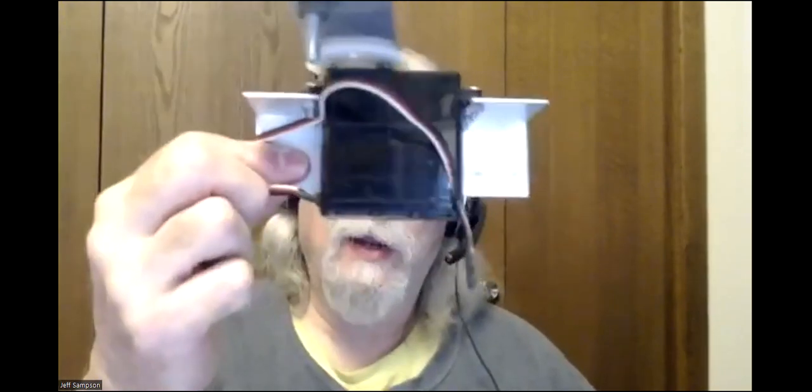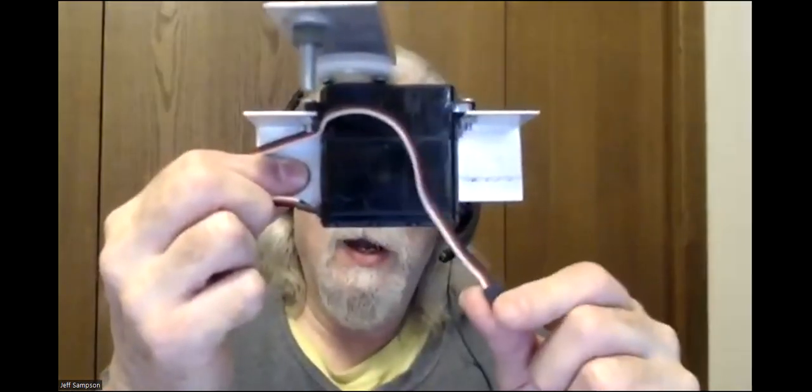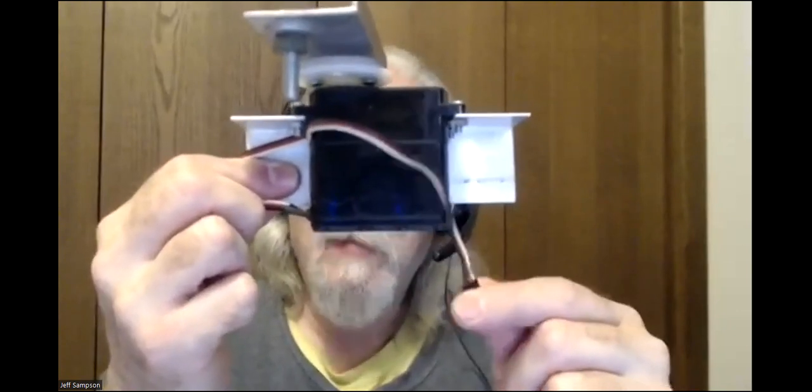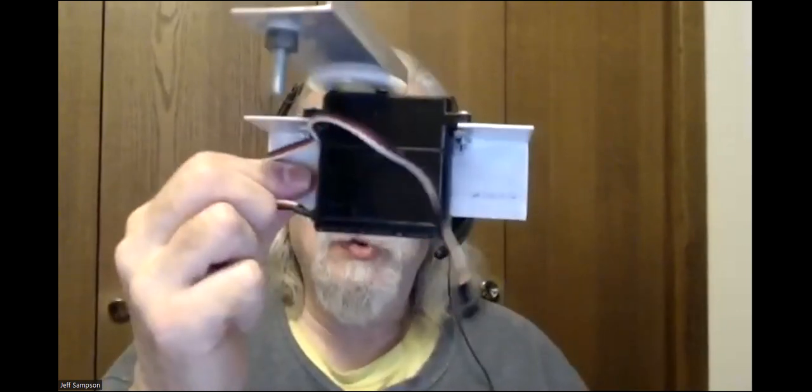And I think it would be relatively universal. Then I could try it on a micro servo and a standard servo and a quarter scale and so forth, just to see how well those things track. So that would be a worthwhile thing to do if I get bored. The only difference is the big servos put 5 volts out. You put them on 12 or 24 volts and they put 5 volts out, and the other ones, like a standard servo like this, you have to actually supply power, like 4.8 to 6 volts, into the connector. So that's the difference between those two.